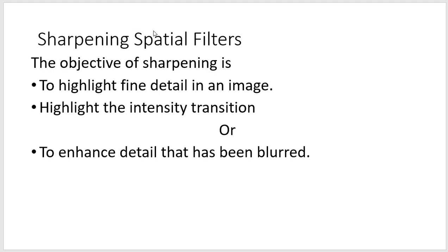Back to EC TechNest. In this lecture, we'll be discussing the sharpening spatial filter. The main objective of sharpening is to highlight the fine details that are present in an image, to highlight the intensity transitions, either from 0 to 1 or 1 to 0, and also to enhance the details that have been blurred.